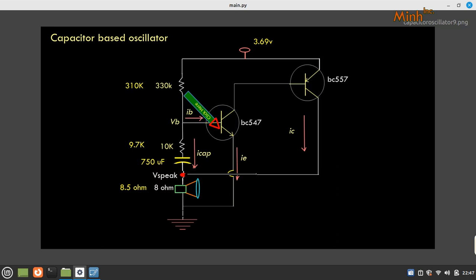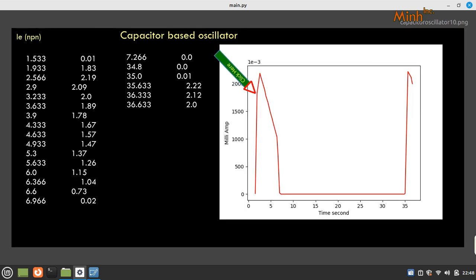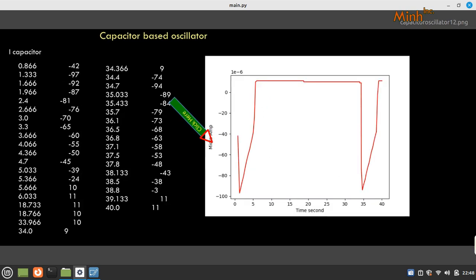junction, the diode junction, the resistance is very low, and the capacitor discharges. So it is a kind of dilemma that the circuit is becoming active, but at the same time the capacitor is discharging through the base-emitter diode junction. So current is decreasing, so the transistor becomes active, but in parallel the capacitor is discharging. If the capacitor is discharged to one level, suddenly it falls, which can be seen. Probably we will see it in the VB. So this is the story of IC.